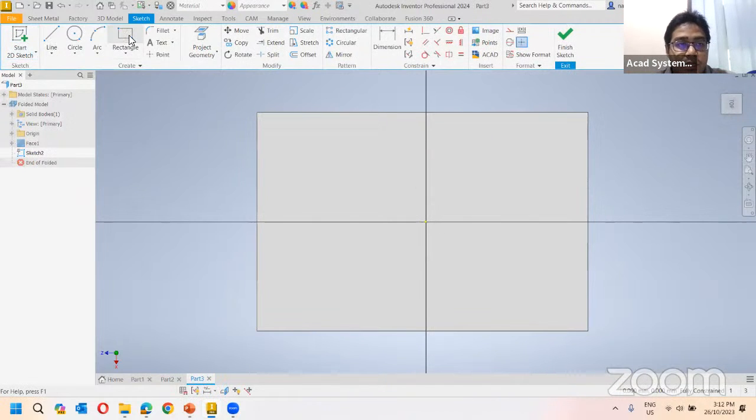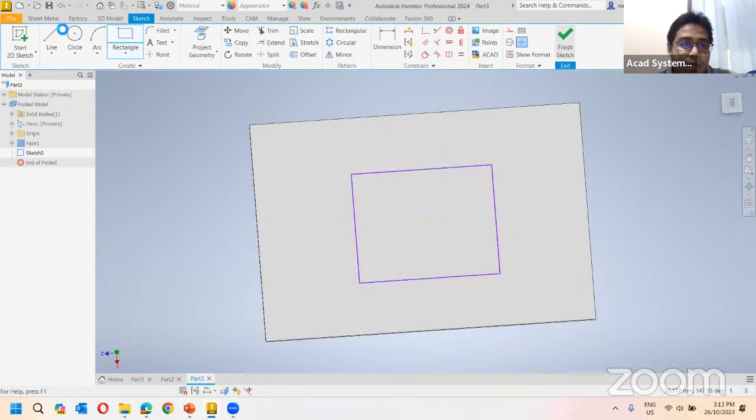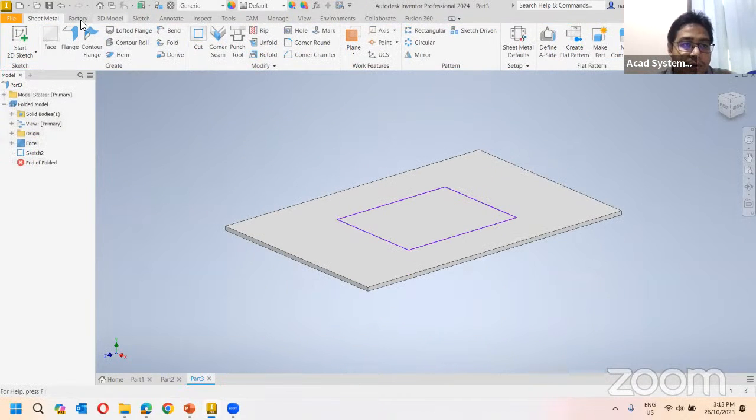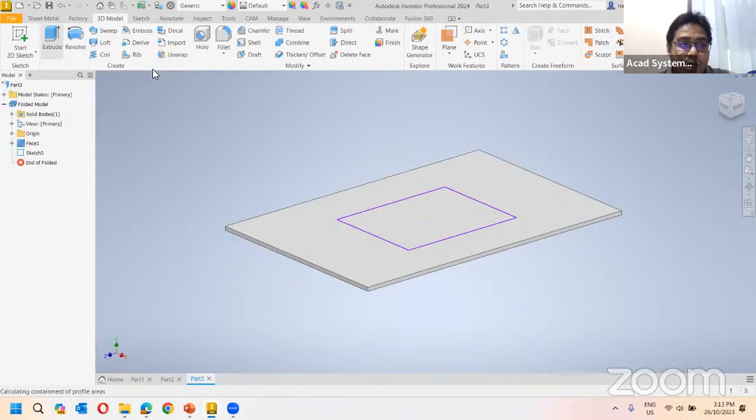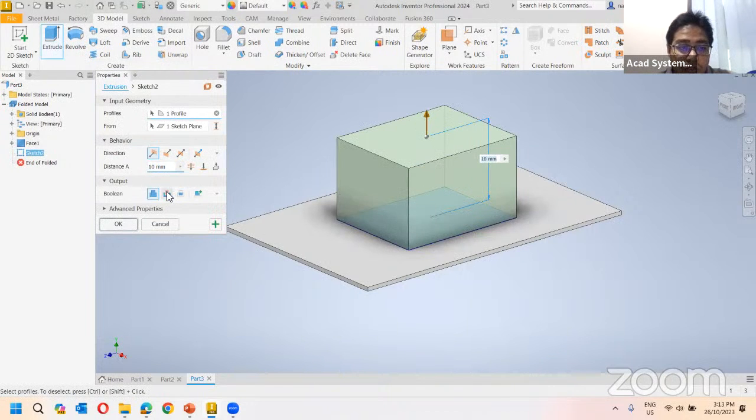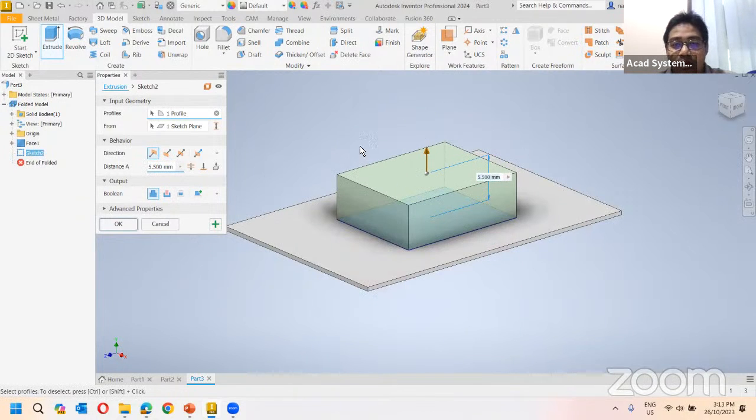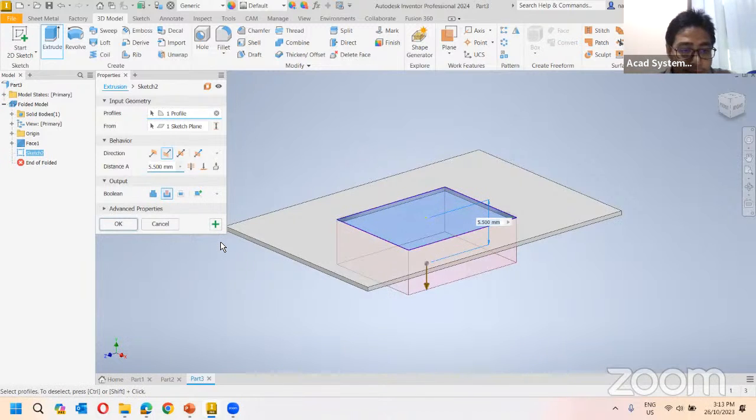So again, the first thing is you can create cuts or extrudes. The one I recommend is to use cut instead of extrudes. What I mean here is not the cut here, but the cut using the extrude. So I recommend you to use cut and not create a joint like this, because usually you will encounter some problem. So to start off, start using cut first. That one will work better.